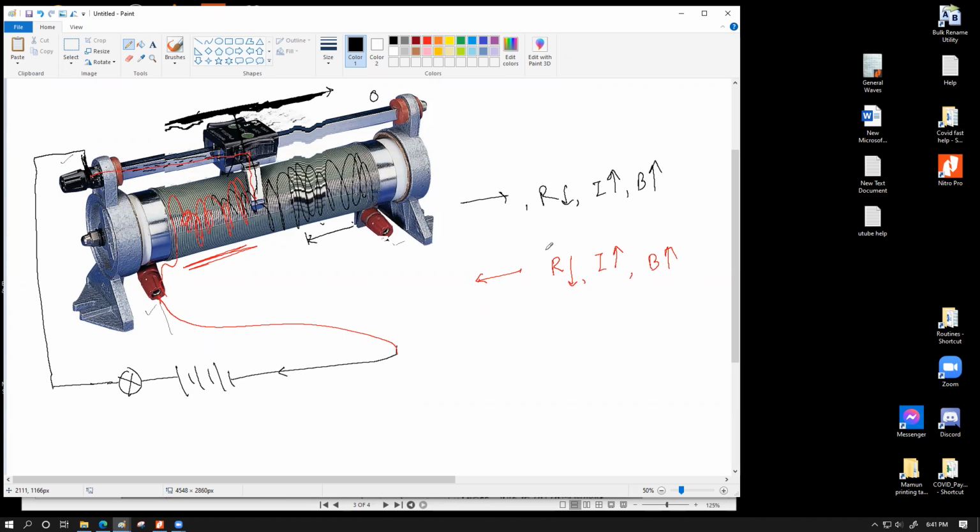You have to simply judge which part of this entire coil of resistance wire is actually a part of your circuit. In this connection, this is the actual part that is working on the left side of the sliding contact. If you connect it over here, this is the active part. The remaining part is just useless. It is not a part of the circuit because current cannot go out anywhere from this point. So current is simply not going to travel through this point. Simple. Did I make sense so far?